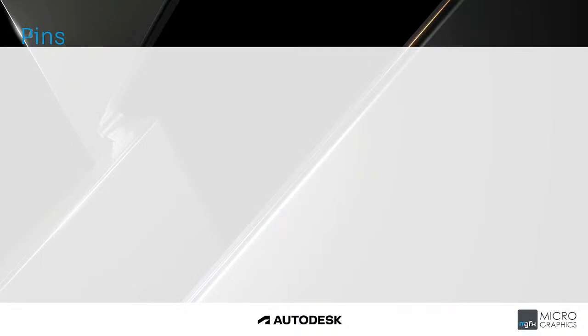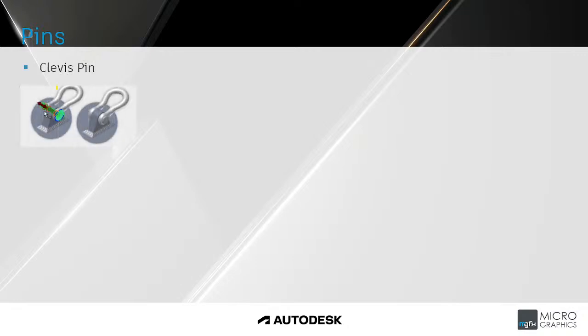So in Inventor you get different pins as well. So the calculation includes a strength check, parts material check, and the minimum pin diameter. So let's have a look at the different pins you get. First you get your clevis pin. The clevis pin calculates, designs and checks clevis pin joints. Then you get the secure pin, design and calculate secure pin loads with the shear.